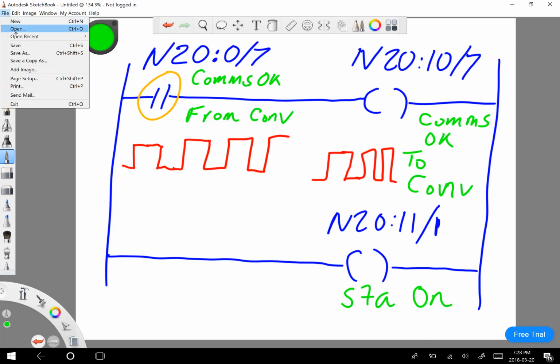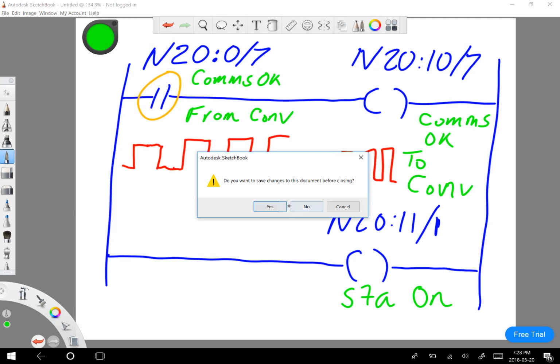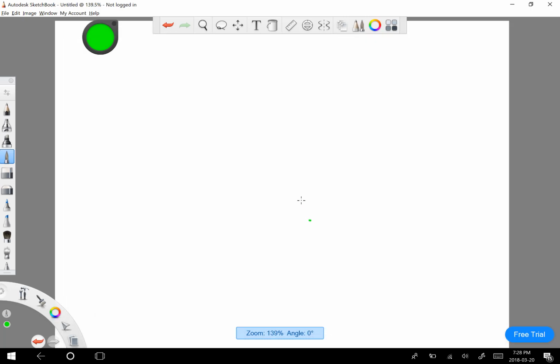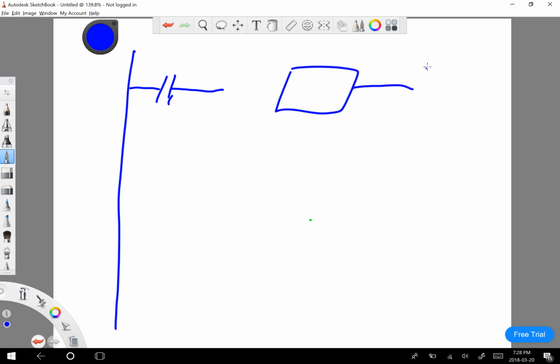The next thing we need to have will basically run those two signals, the pallet present and then the complete. So in our logic we have our sequencer, the very first line of our sequencer, well, one of the first steps. We're going to move a 1 if we are equal to 0. We have everything at home.